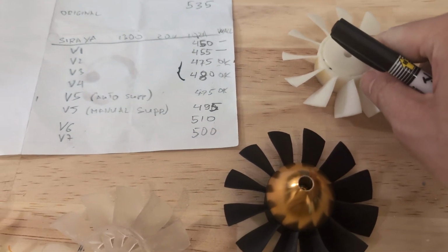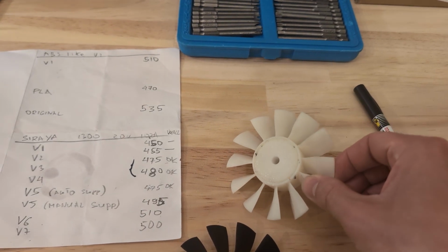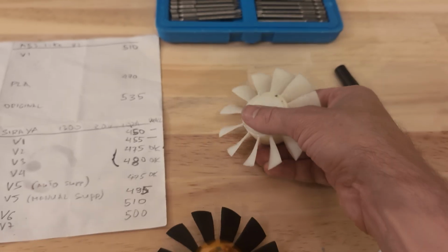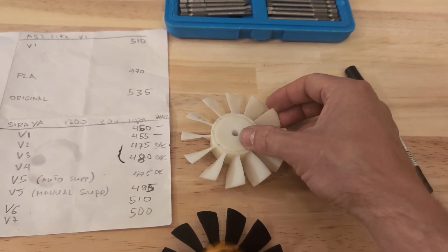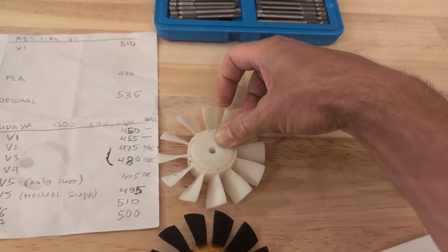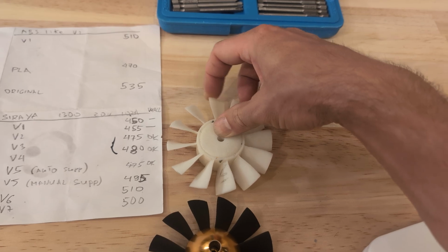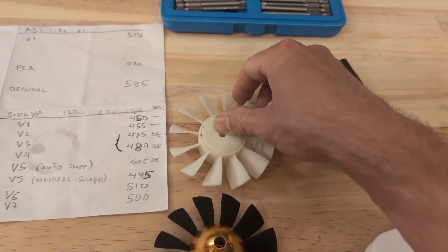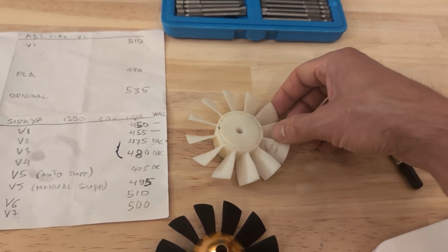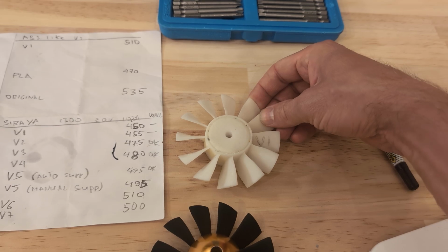But the problem is, remember I told you, it bends easily. When it spins at very high RPMs, the load is so high, the pressure is so high, that those props bend like this. And they lose thrust. So for low power, it's perfect. But if you want a lot of power, your propeller blades have to be very strong. They cannot bend, or if they bend, they must bend just a little.